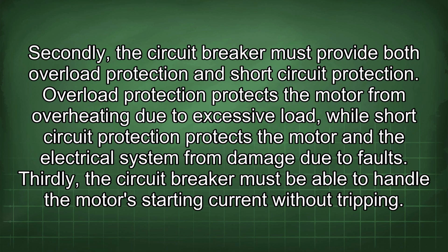Secondly, the circuit breaker must provide both overload protection and short circuit protection. Overload protection protects the motor from overheating due to excessive load, while short circuit protection protects the motor and the electrical system from damage due to faults.